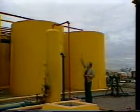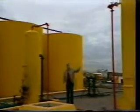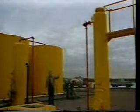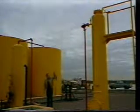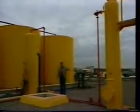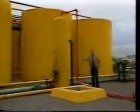The gas drawn off the top has as its first stop to go to this iron sponge, which collects all H2S in the gas, if there is such H2S in this gas, and it happens to be in some of the gas produced here. The gas passes through the iron sponge downward, H2S is taken out, and the clean gas now travels through this red line and off to be metered.